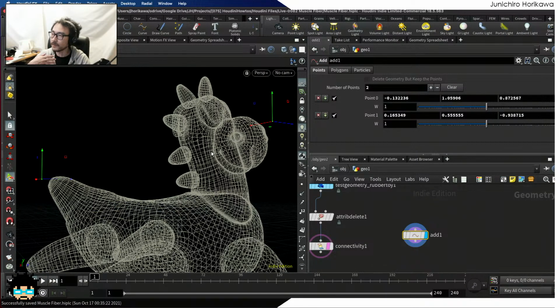Then store this distance value as an attribute to each point, then use this distance to calculate the gradient vector using a measure node or something. Then I can use that vector value as the guide to move the point from the starting point in those specific directions to create a space filling curve.